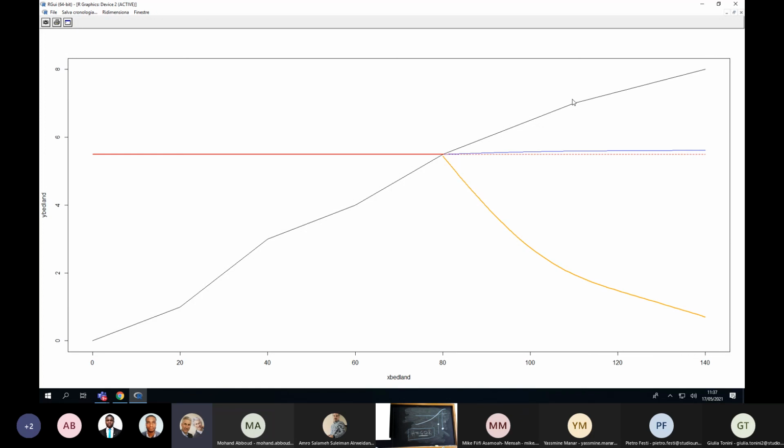The most complicated thing to understand in this exercise is the refinement of the coordinates and the smoothing. This is the only thing that is new for you. Otherwise, if you start from the coordinates of sea level, land, and fresh water, you just compute the elevation of fresh water above the sea level, and you multiply it by 40 in order to find the depth of the interface. It's very simple.